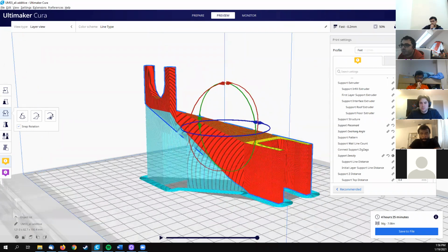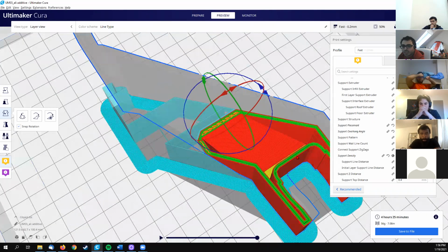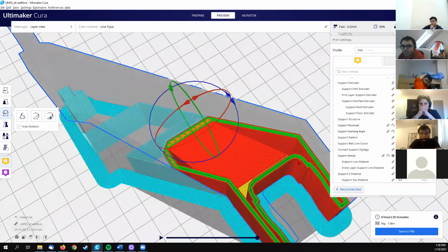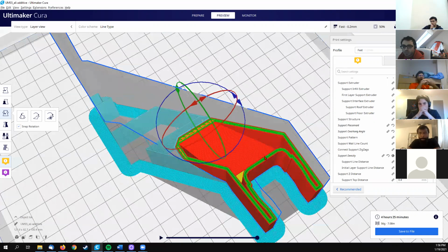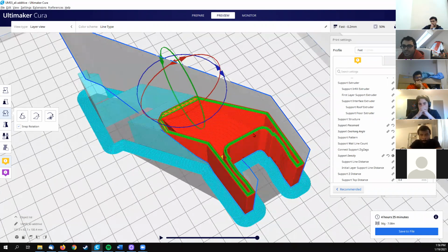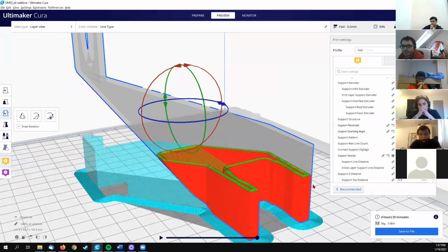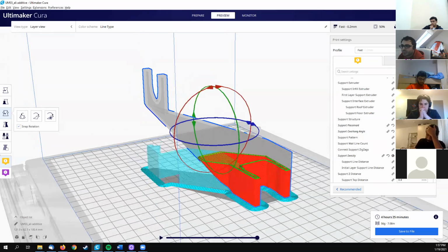Now if we go into the base layer, if the tension is in this area or in these corners, the tension is along the direction of the line. That's what I was trying to explain: you have to orient the part when you slice it, so you have the tension along the line, not perpendicular to the layers. If the tension is upward, perpendicular to the layers, then you'll have delamination, okay? So that's something you need to consider at the base for such a part.